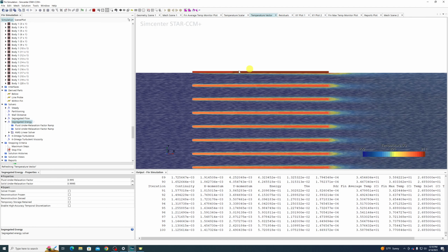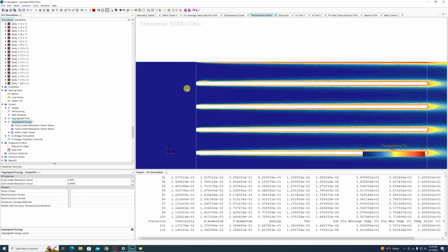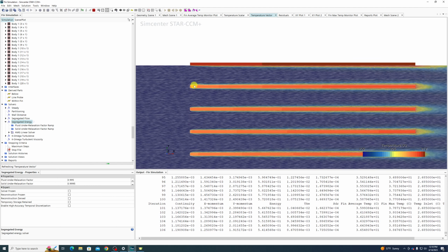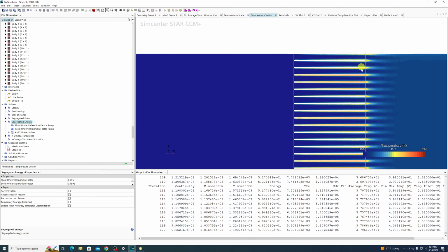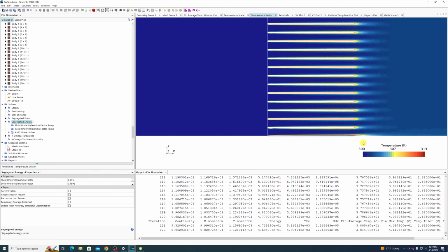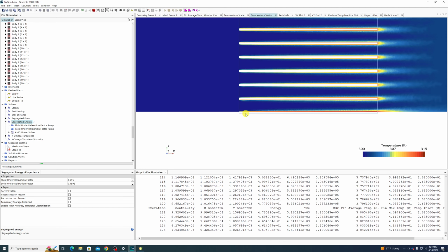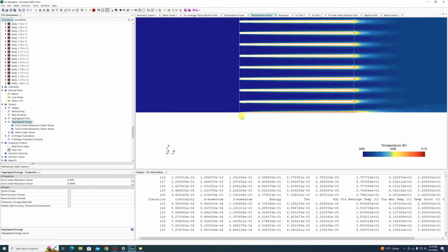But what it's actually doing is there are no real boundary conditions in here. This is purely saying, hey, I have a solid aluminum fin. I'm generating heat. And you can actually see the fins have a temperature gradient to them, right? They start out relatively cool, and then they increase in temperature towards the back. And then these fins out here are just blisteringly hot because they only have one side.